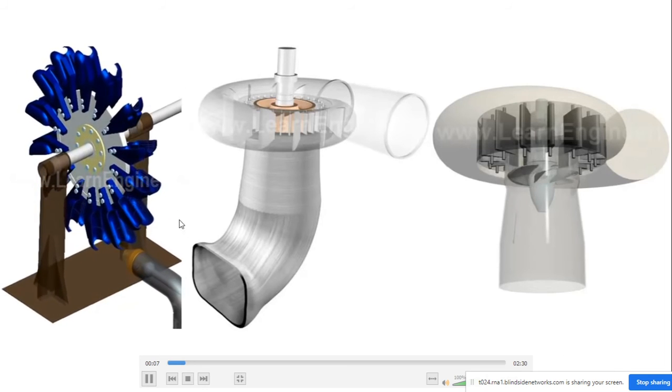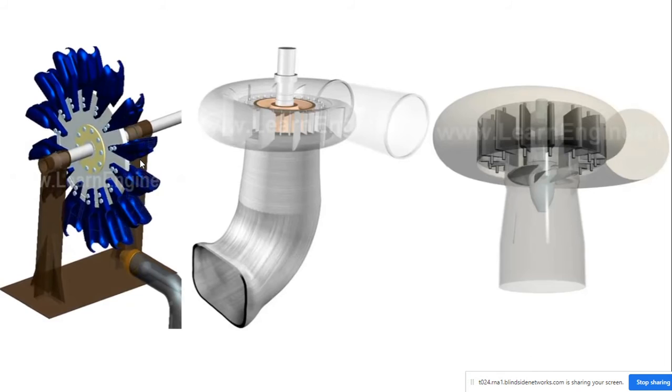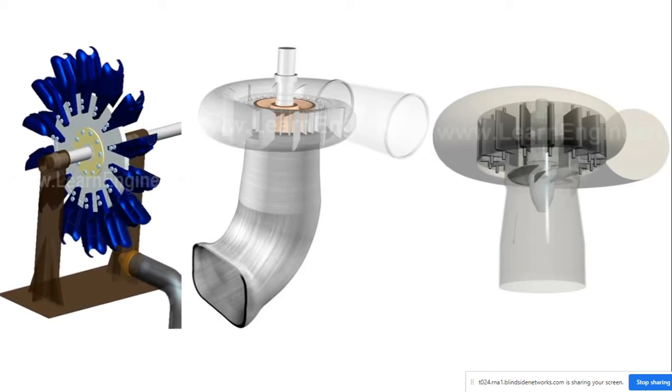In this video, we are going to compare turbines and see when to use which turbine. So if we see the Pelton wheel turbine, this is my runner, and on this runner I have placed the buckets either with the help of nut and bolt, or sometimes I am going to use casting also. The buckets are directly cast in the wheel. The wheel and bucket is a single unit, but for large applications we are going to use nut and bolts. So if one bucket is damaged, I can replace the single bucket. If it is a casting, then it is quite difficult to repair it.